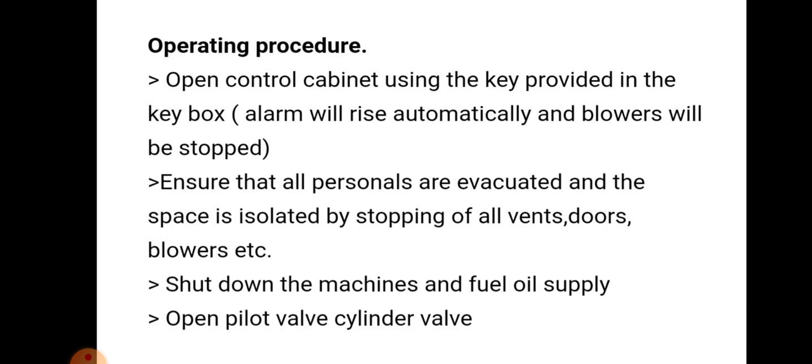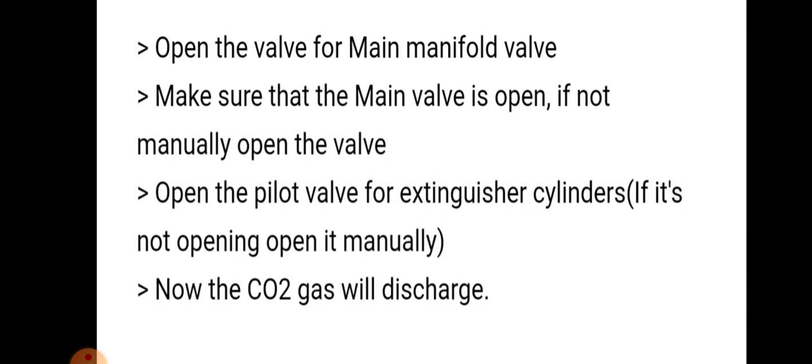Open pilot valve, cylinder valve, etc. Open the valve for main manifold valve. Make sure main valve is open. If not, manually open the valve. Open pilot valve for extinguisher cylinder. If it is not opening, we can open it manually. Now CO2 gas will discharge.